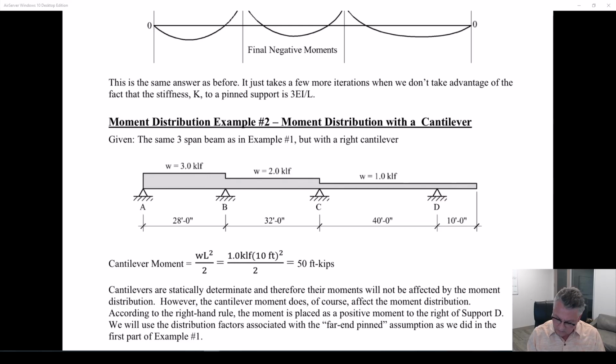In cast-in-place concrete, at some point the cantilever will get long and it will start drooping. This will hang down, create some problems, creep over time. Post-tension concrete, we solve that. We actually just use the post-tensioning to pick up the sag or the deflection, and we can make ours flat. So we're showing off a little bit, it's true. But when you can, you do it.